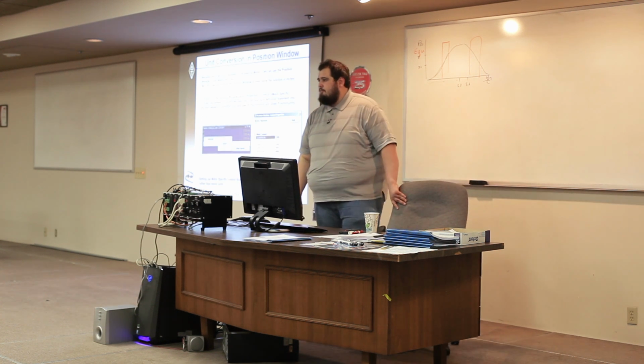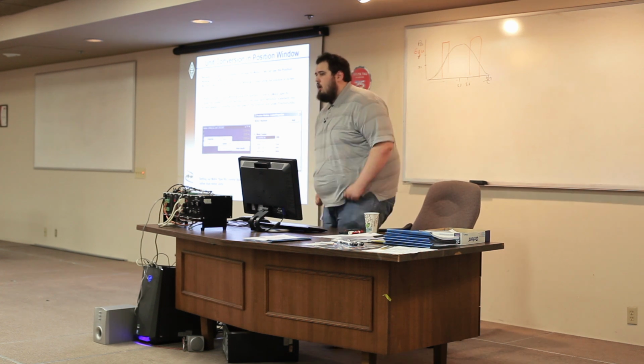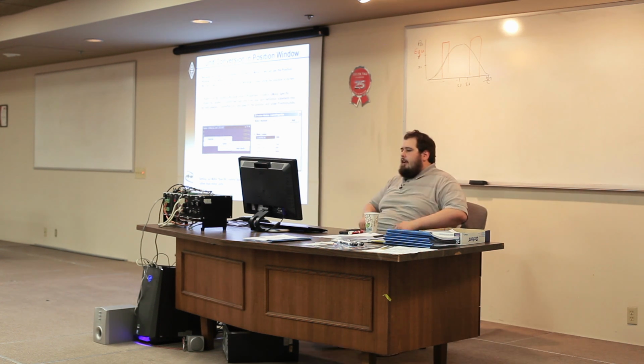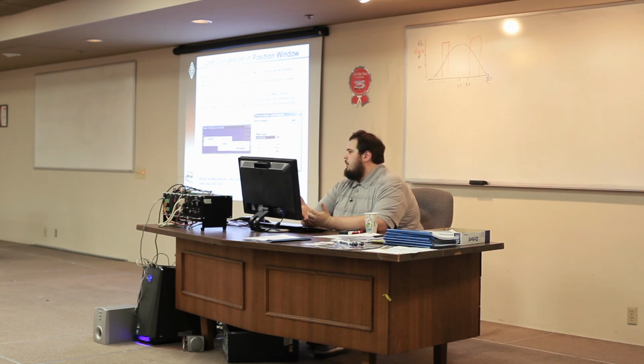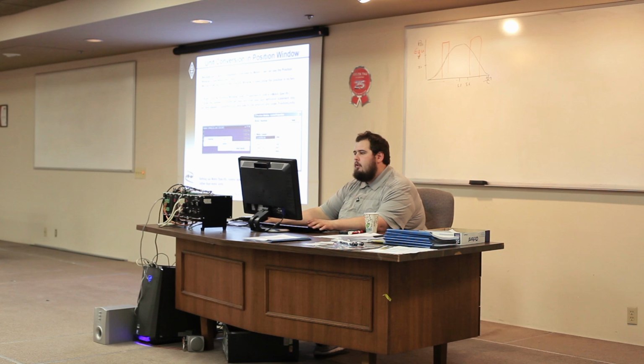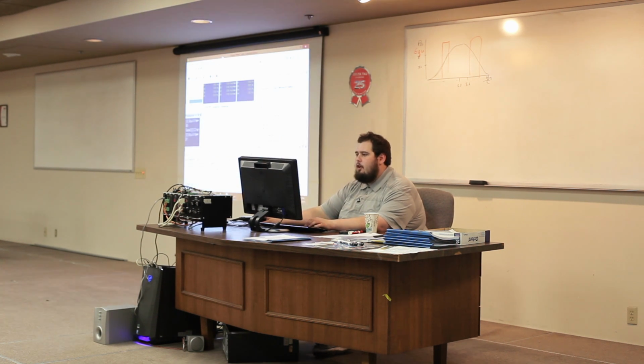So this is as good of a time as any. I'm going to ask for your attention really fast and just show you how to do something in the IDE window. Because now we're dealing with a kinematic axis, or not much of kinematics, admittedly, it's one-to-one, but we're dealing with axes rather than motors. We want to change our position window to actually show the units that we're dealing with. So, in the IDE, I'm going to come over to my position window, right-click somewhere in the blue of the window, and go Properties, Control, Motor Specific.